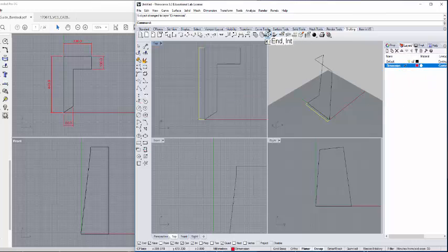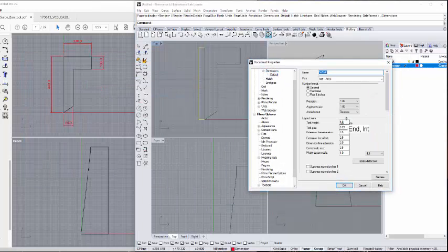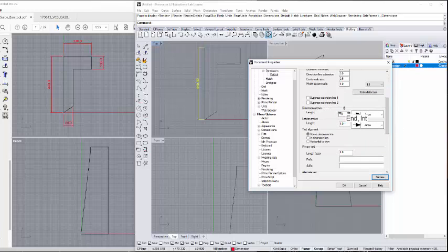And then remember again how to change dimension style. Okay, let's say we go to dimension style, go to edit, text height, maybe I choose 5. Okay, can't even see 15. Okay, slightly better. So right now I need to go down to my arrow size.